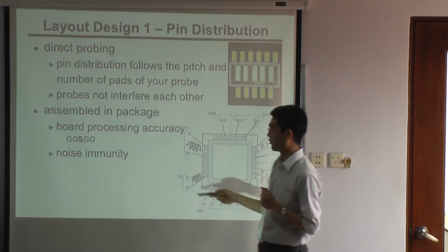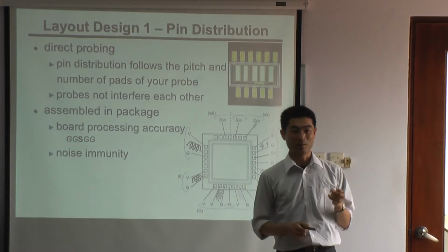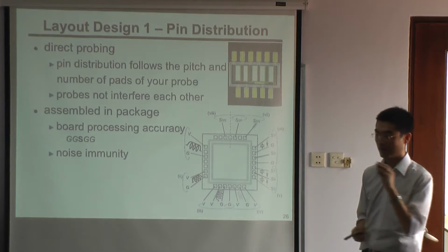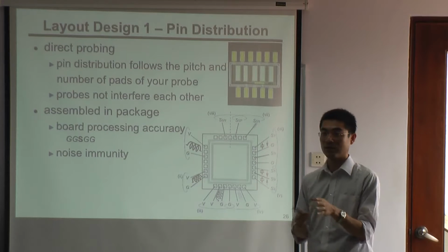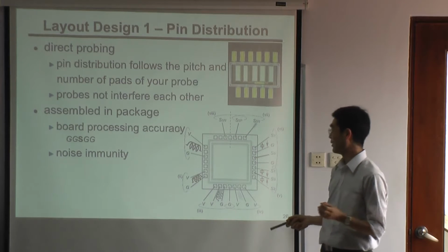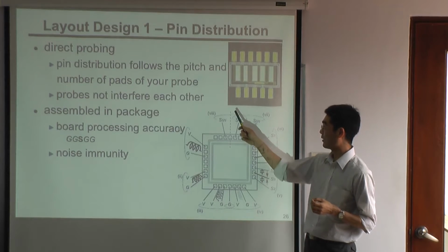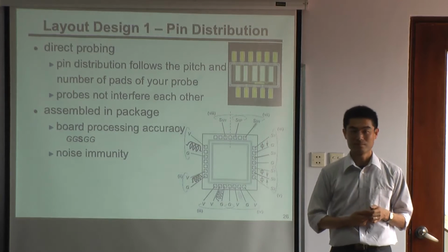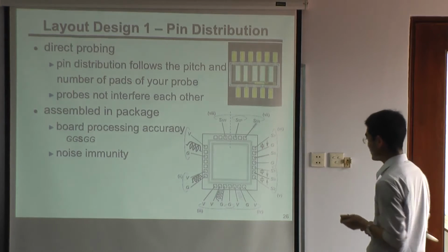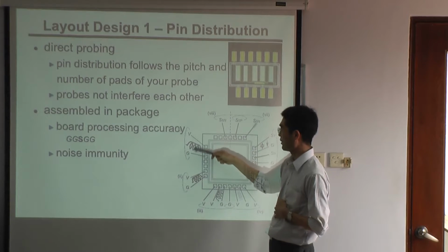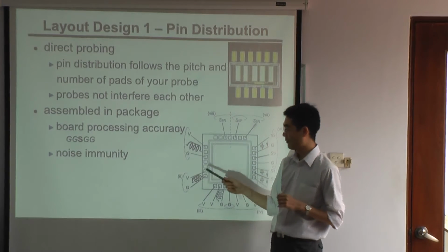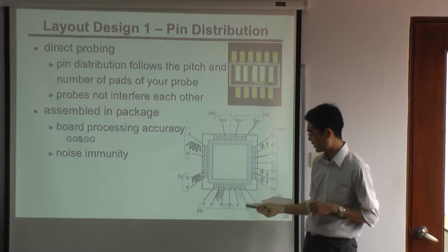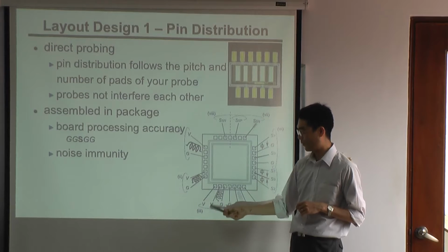And also you have to consider the noise emission: how many capacitors you have to put on the board, and whether important signals are sandwiched by ground, or you have to take into consideration the symmetry of the signal and signal. And again, the V and G should be side by side. And if you have multiple pins, VG VG is better than VV GG.